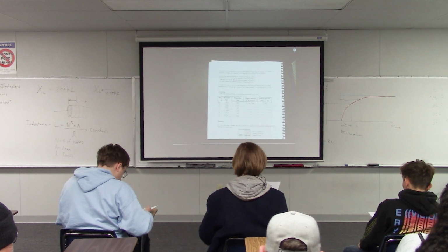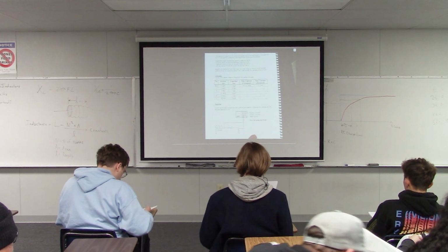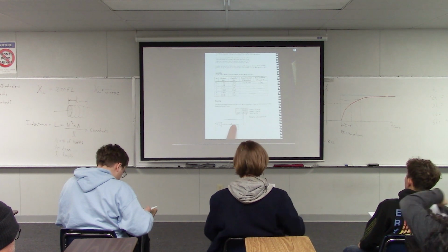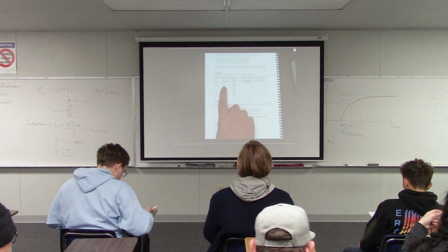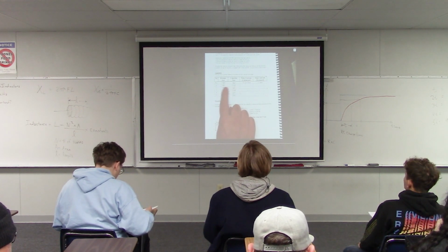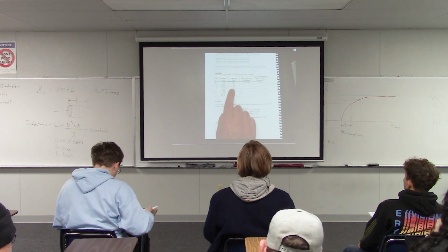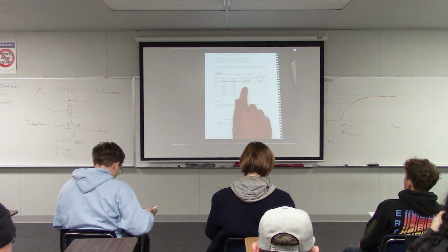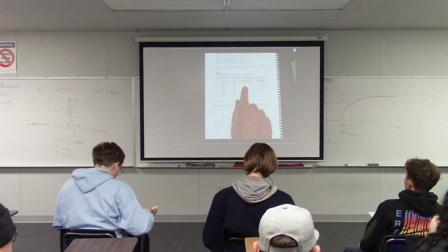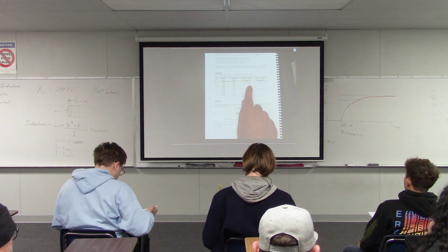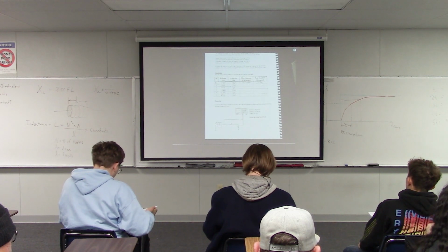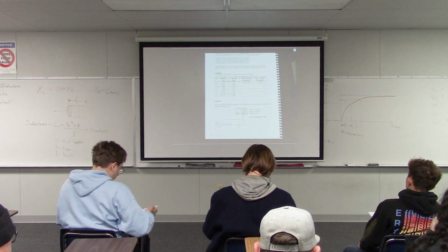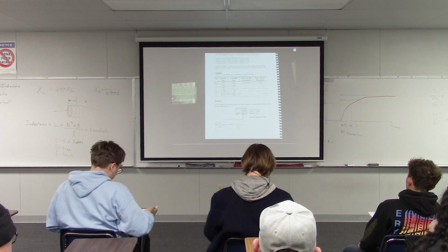And then you're going to build a circuit that looks kind of like this on a breadboard. You're going to use these different combinations of resistors and capacitors. And for each one, you're first going to calculate the time constant, and then you're also going to measure the time constant. Okay?